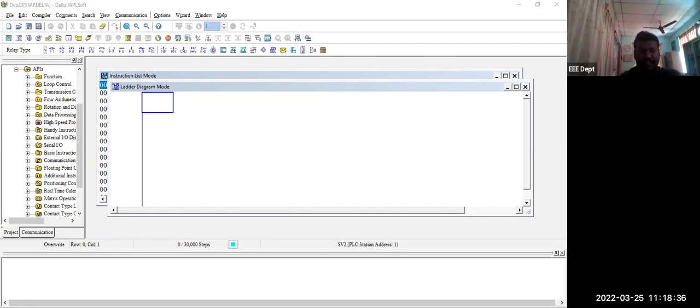After that, the motor will be in delta connected mode. So running condition is delta connection, starting condition is star connection, changing at 80% of the rated speed, and at running it is delta connection mode.